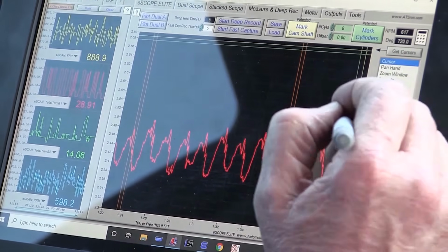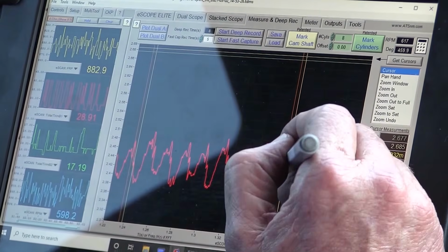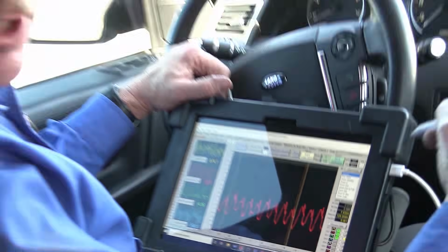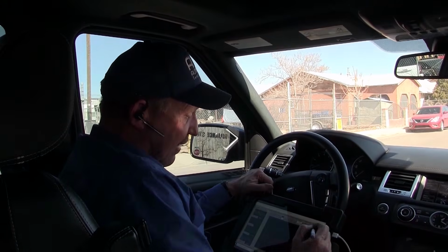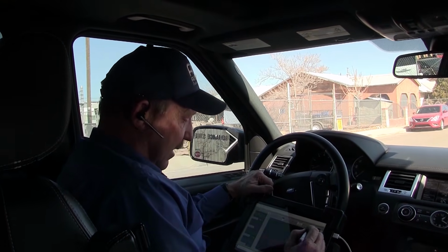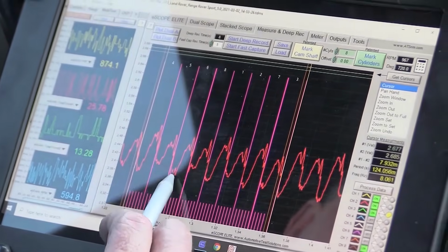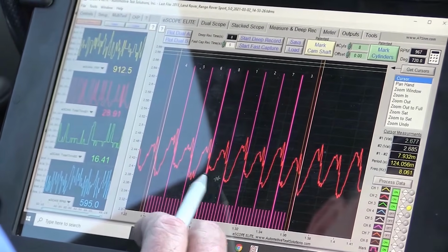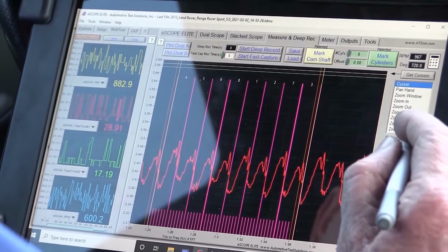And this is the pressure running back. Now, if I had a fuel problem, if I had aeration going in, I would have both pumps affected. But I have every other lobe being affected. So you can see how these are real clean and they're all sort of even. And I still see some unevenness, but nothing like where we have our failure.